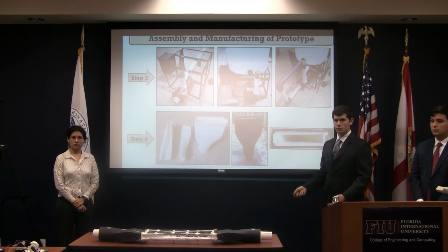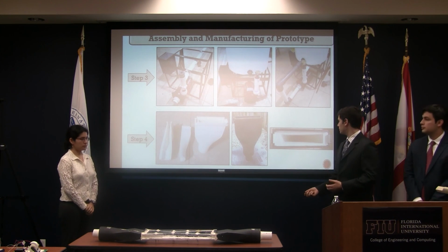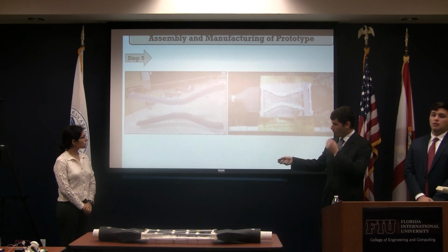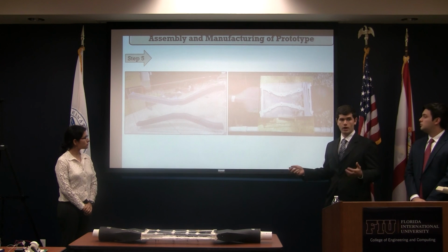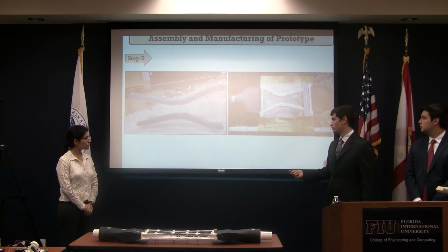Then we 3D printed, as you can see here, the diffuser and the reducer, and we coated them with black sealant to avoid leaks. Then we CNC'd the walls of the nozzle and glued them to the acrylic plates and bolted them to ensure that they withstand the pressure.